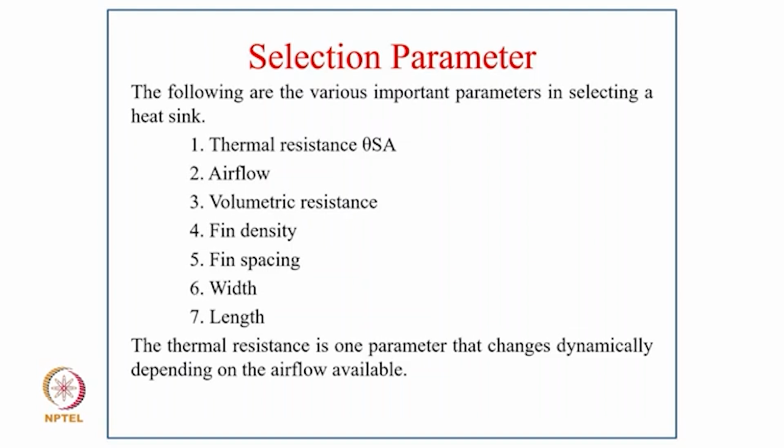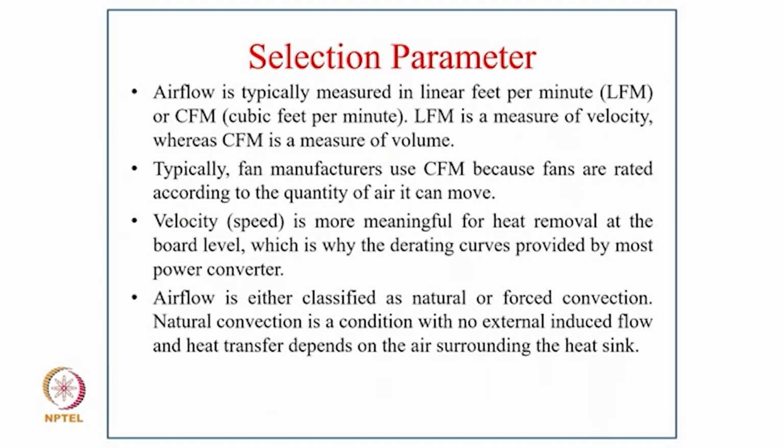Thermal resistance is one of the parameters that changes dynamically depending on the airflow available. Airflow is typically measured in linear feet per minute, LFM, or cubic feet per minute, CFM. LFM is the measure of velocity, while CFM is the measure of volume.